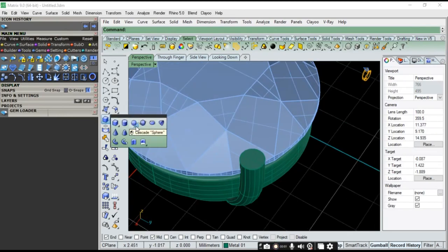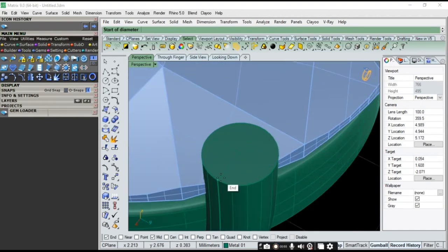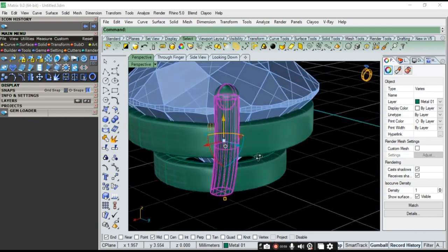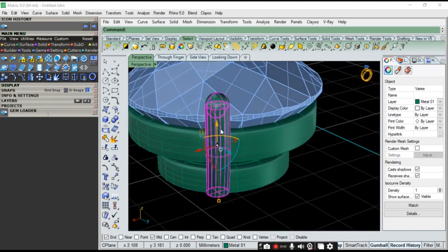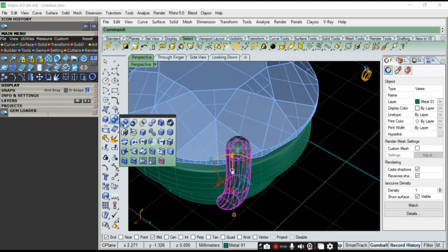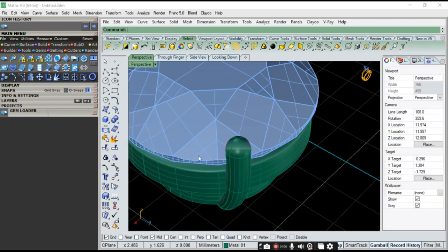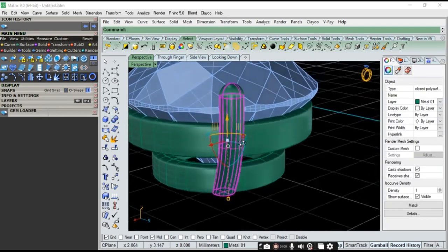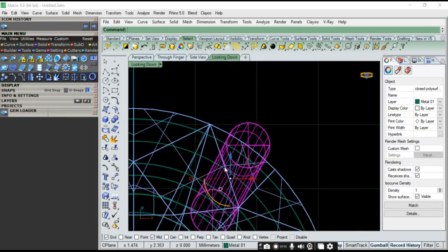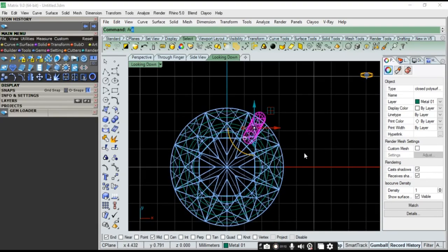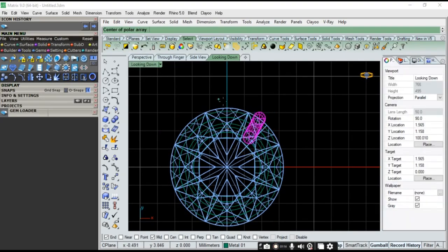then add sphere using diameter option. So we have to click 2 points, it will automatically set the top round portion. Then use boolean union operation, so it will merge both the objects into one. It will boolean 2 objects into one object.